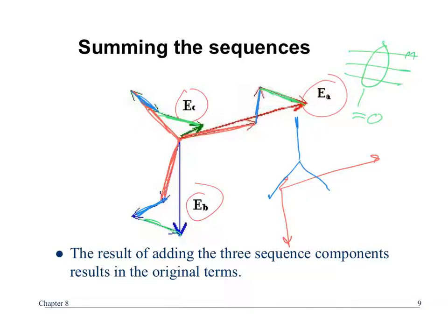Now, what they do is they just put a CT on each phase, and these CTs are Y connected, grounded, and then inside the relay, it takes the ABC and spits out 0, 1, and 2. It just does the math. It does literally linear algebra to calculate what the negative sequence is. So you don't have to do those donut CTs anymore. All the newer stuff that you've seen in the last probably 5 or 10 years, you don't see overall window CTs anymore because you can get the same result. You just do it mathematically.